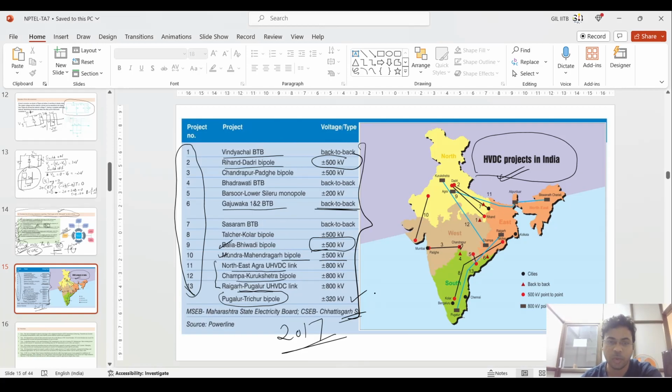Suppose you want to implement this DC link. Suppose you have a certain converter, and you need a converter in the reverse direction to take it back to the voltage source side where the power is generating. So this kind of structure is said as the back-to-back converter topology.